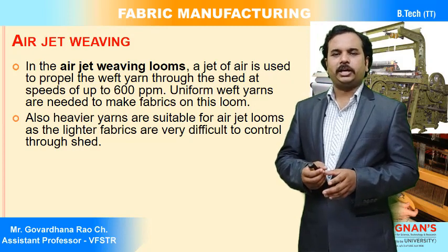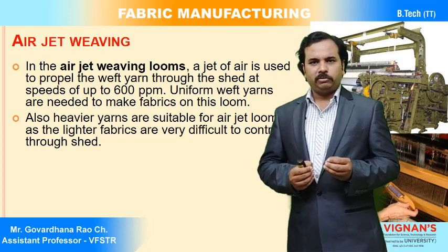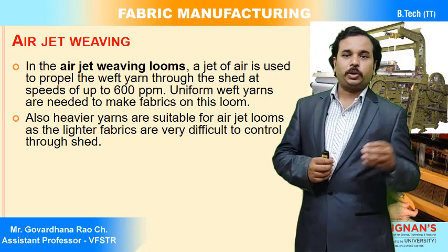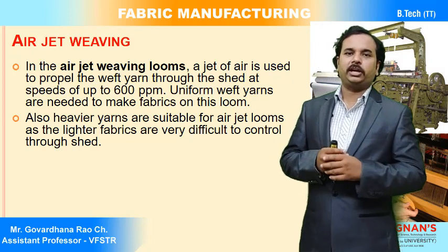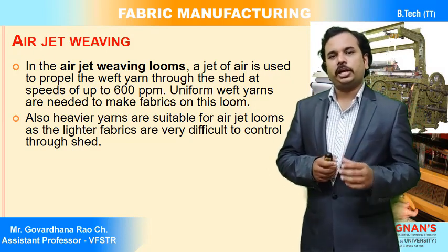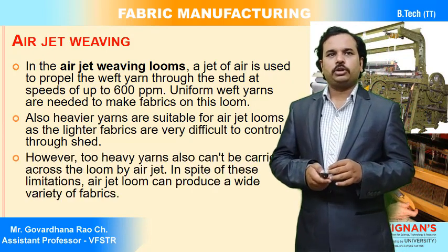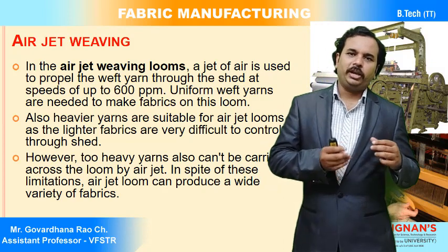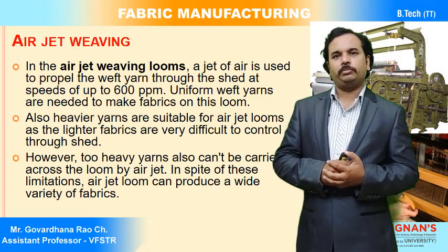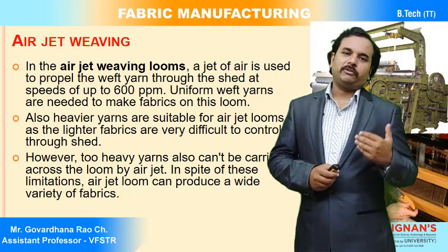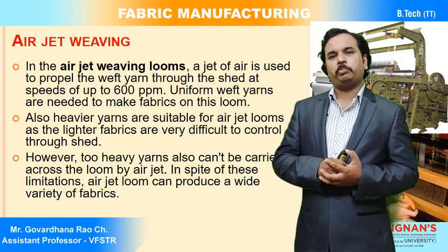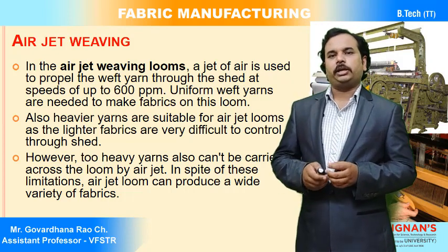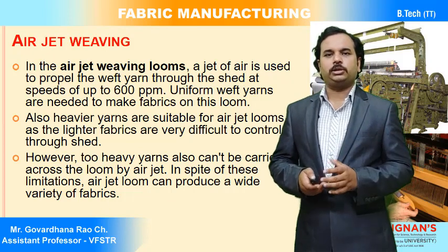Too fine yarns are somewhat difficult and will have some problems, in carrying or controlling the weft yarn insertion in the shed by means of air. However, too heavy yarns also cannot be used, because very coarse counts make the air consumption and the force required to pull the weft yarn from one side to the other complicated. That is why too heavy yarns are also not possible.